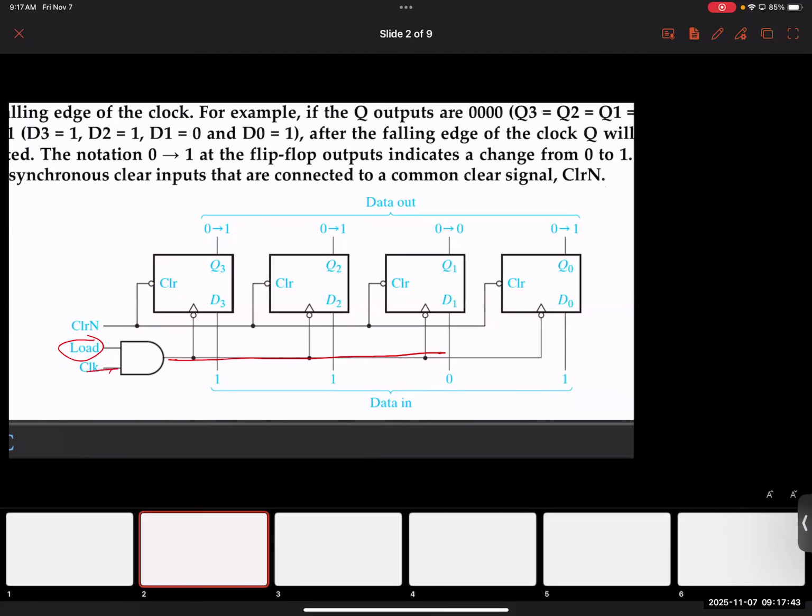So remember, this clock signal is a very important and very big signal channel that is routed across thousands, if not millions of components. So you don't just turn off the clock, but you can turn off the clock effectively in certain sections using this type of trick.